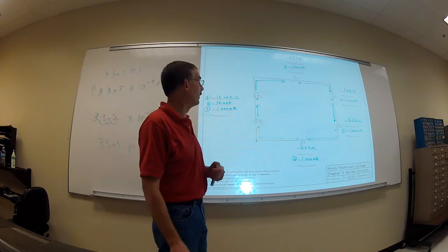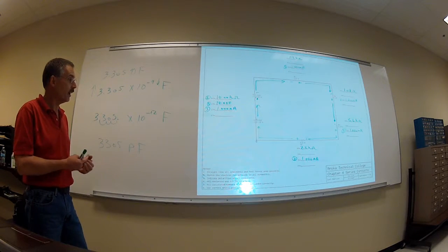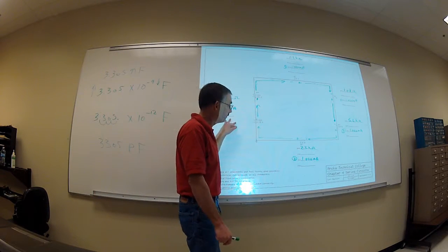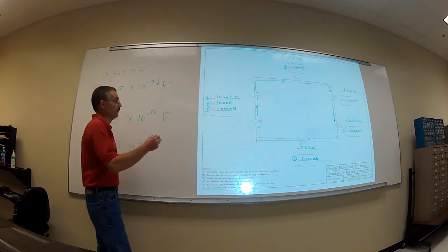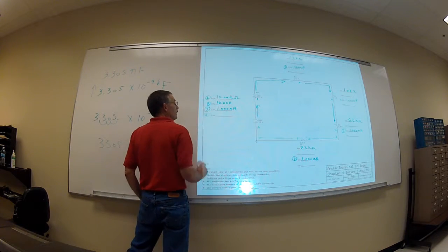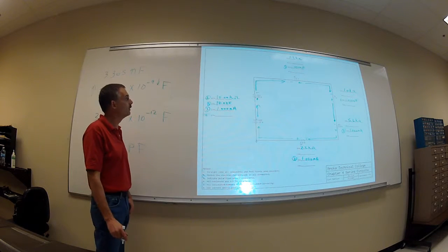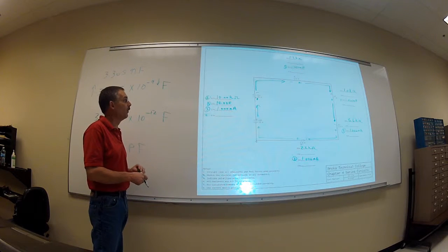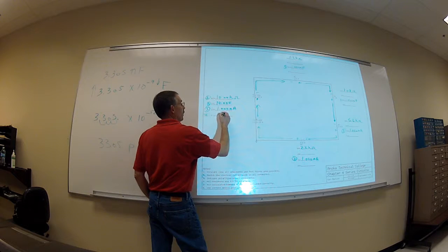We already had that filled in, because when we have a complex circuit, we might forget what that current was and end up having to recalculate it a second time, especially when we get into series parallel circuits. All right. Now we can find step 4, which is our power. How are we going to calculate our power? Yep, I times E or V. And what do we end up for power total then? 10 milliwatts.